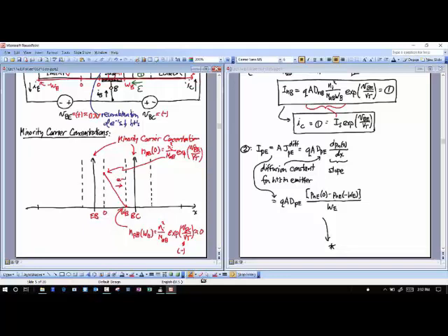That's a large number. That will make this whole thing smaller for the emitter side. And so if I were to draw where that concentration is, I would draw it all the way down here. So if the electron concentration in the hole that was injected into the base is all the way up here, then the hole concentration injected into the emitter is all the way down here. Okay, and so it also is going to go down as we go across the emitter, except by the time I get to the edge of the emitter, and let me call this 0 there and call this W minus WE, that's the whole emitter length.